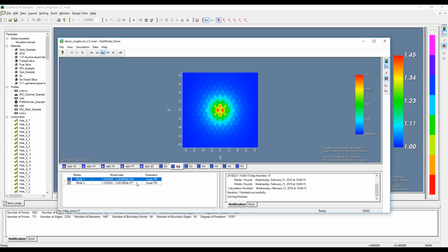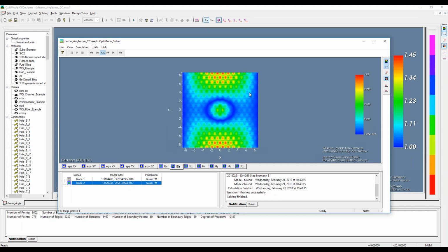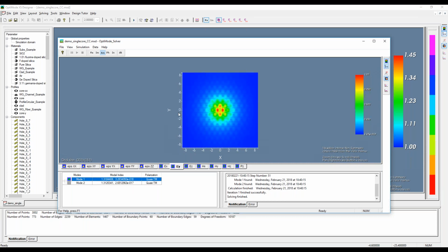And then it doesn't find the x-polarized mode because we chose the boundary conditions in such a way that that mode wouldn't actually exist in the structure. But it does find some higher order mode that's interacting with the boundary conditions at the top and the bottom. And so for the structures in the paper that were symmetric like this, the three individual cores, I used that to exploit it. I did the symmetric boundary conditions.